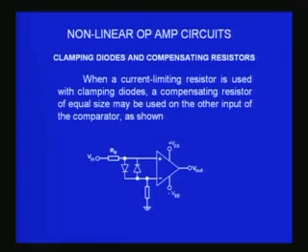So this input offset voltage, generated due to input offset current passing through the resistors connected to the two input terminals, can sometimes exceed 150 microvolts on the plus side or on the minus side. When that happens, the output will switch state even though it should not, according to the input voltage that I have applied at the input terminals. I hope you realize the situation.